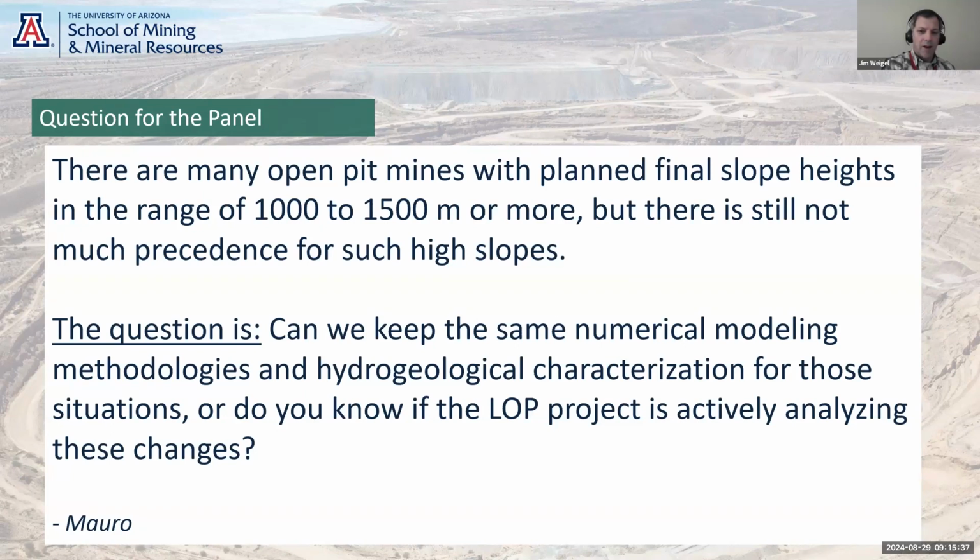We still have to have hydraulic inputs, so you still need to have the pumping wells, or for us, we operate a bunch of wells into underground workings that can affect very large extents of the rock mass. And we use kind of natural pump tests, if you will, and they happen anytime one of our big pumps goes down. The motors usually burn out, or we wear out impellers, and it goes off for 2 to 6 weeks, say. And so we have our recharge period. So that's kind of like our giant slug test, and we're watching the waters come up.